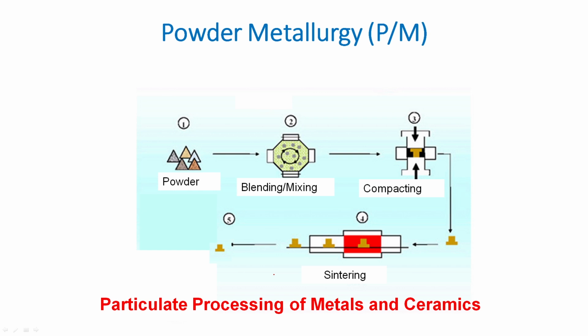Compacting is to make a component of the shape you want in a green way. Green means the strength between the loose particles is very low. Then you have to make it strong. You have to sinter it at high temperature. High temperature allows the diffusion of atoms to happen, and that can lead to good sintered products. This is in a nutshell what the whole process is.